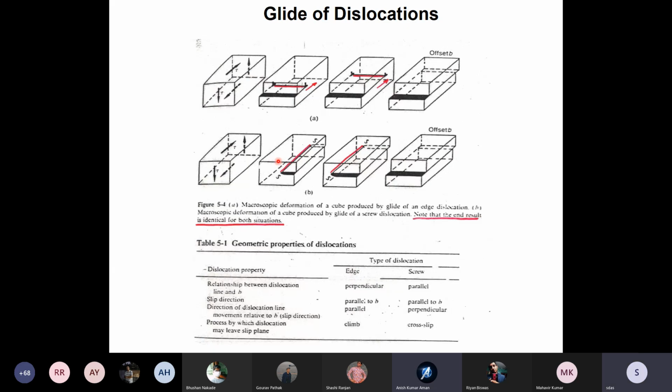Now tell me why it got heated. Every time you twist it, you apply a shear stress to it and generate more and more dislocations. How dislocations get generated will be taught tomorrow. This dislocation is associated with energy, and that energy is manifested in terms of temperature rise.